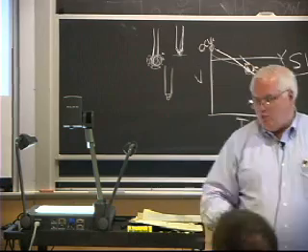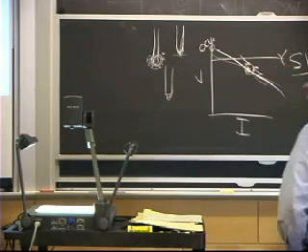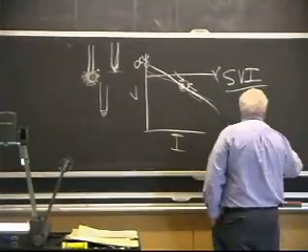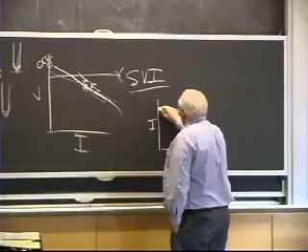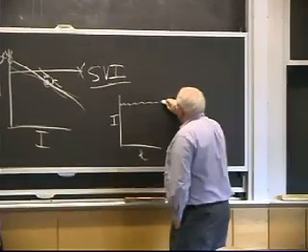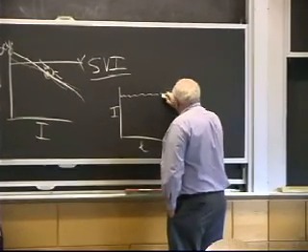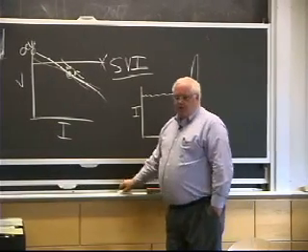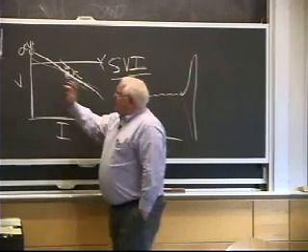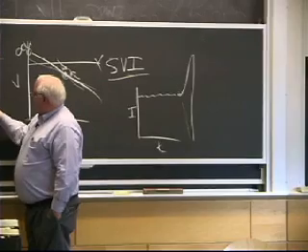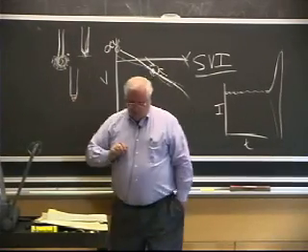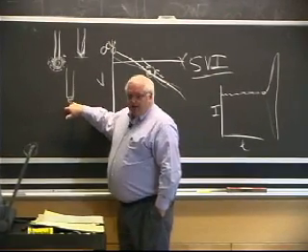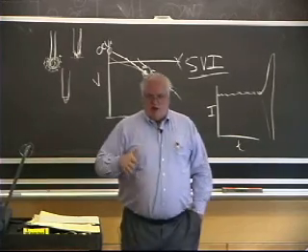So anyway, let me go back to finish up this. You squeeze off, you put a pulse of current in. If you were plotting the current versus time, you're running along at a few hundred amps, and you tell the machine to stop, and it doesn't just drop the current. It gives a huge pulse, and then it drops the current. And that huge pulse knocks the last liquid drop off there, leaves a little bit of liquid, but hopefully leaves a little bit of a point, and you keep your shielding gas going long enough to let this thing cool down and solidify without a heavy oxide.